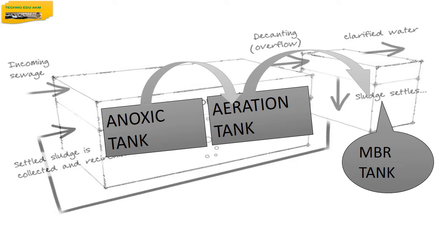Roots air blower, usually used for the aeration tank, sucks the air from ambient and discharges it into the aeration tank to sustain the bioculture for biodegradation of organic load. It is also used in the equalization tank and sludge holding tank for proper mixing. The Roots air blower for the MBR tank sucks the air from the atmosphere and discharges it into the MBR tank to sustain the bioculture for biodegradation of organic food.